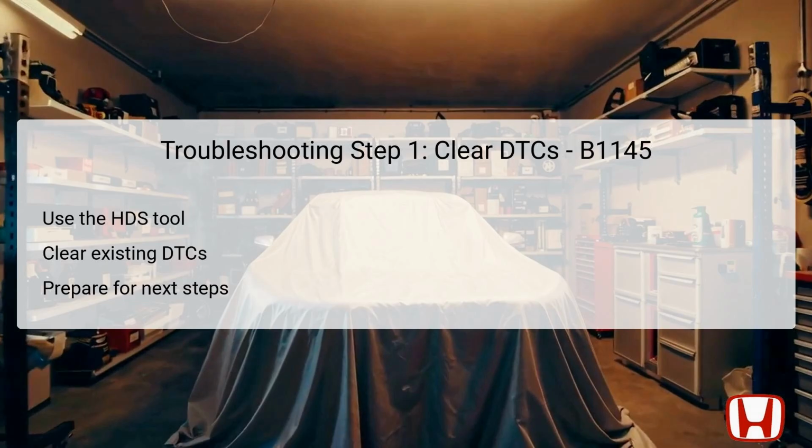This step is important to ensure that when the vehicle is retested, any new codes will directly relate to the current state of the vehicle and aid in diagnosing the issue accurately. Clearing DTCs is a foundational step for an effective troubleshooting process.